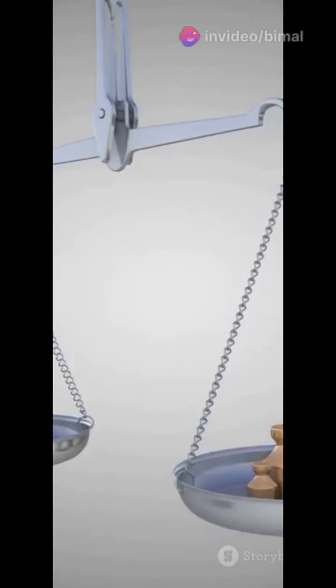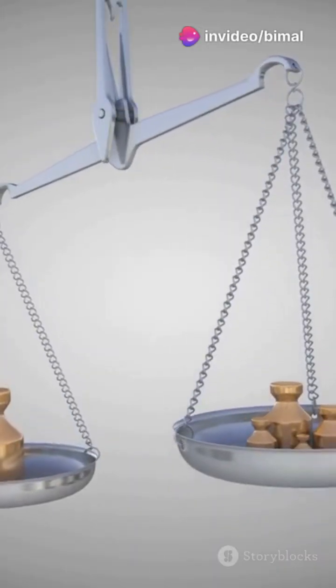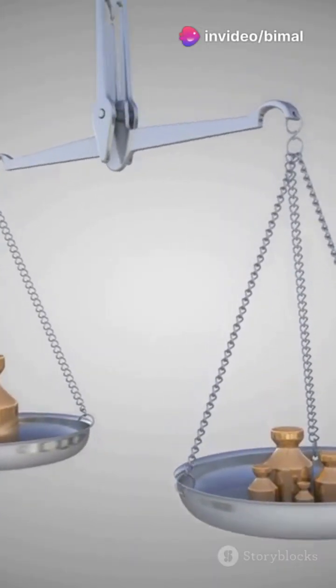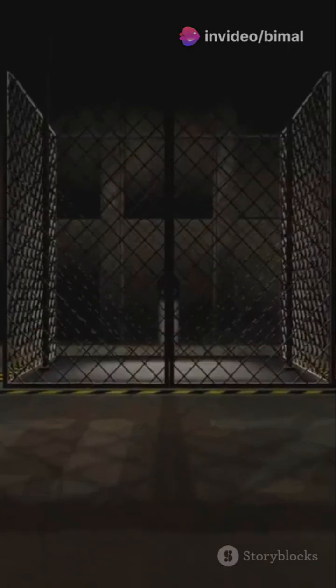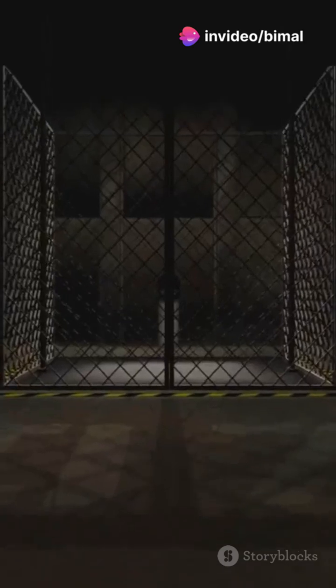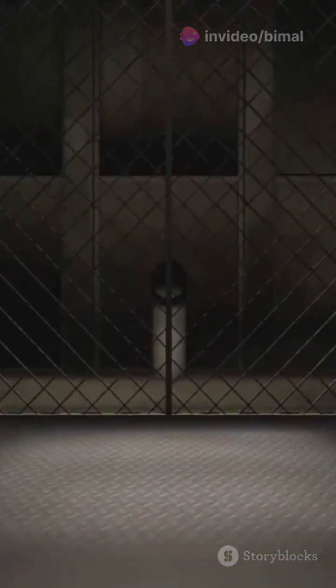Now that we've covered limit switches, let's move on to another critical safety component in PLC-controlled elevator systems: load cells. Load cells are used for overload detection. These devices measure the weight inside the elevator and send signals to the PLC if the weight exceeds a certain limit. When the load cells detect that the elevator is carrying more weight than it should, they trigger safety mechanisms to prevent any potential hazards. This could mean stopping the elevator from moving or alerting maintenance personnel to address the issue. The PLC processes these signals and takes the necessary actions to ensure the safety of passengers.